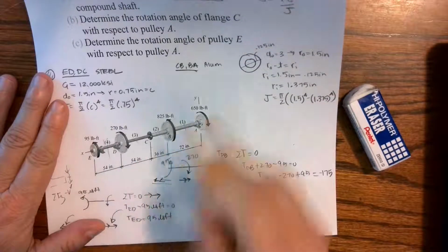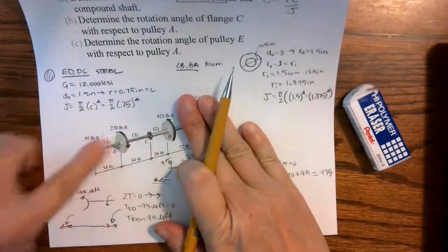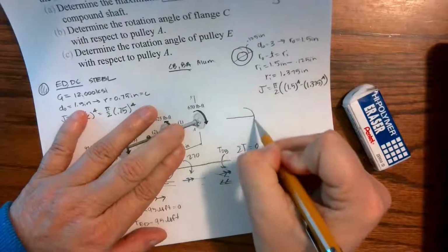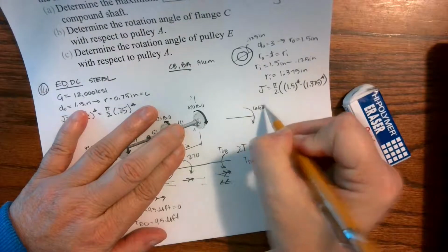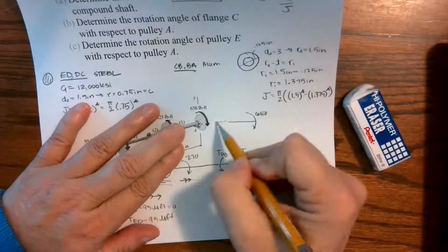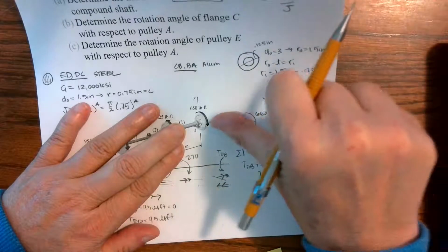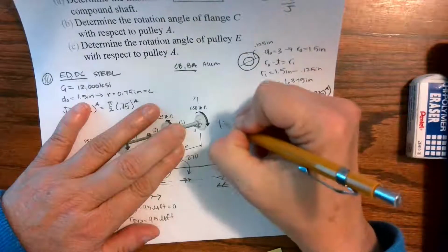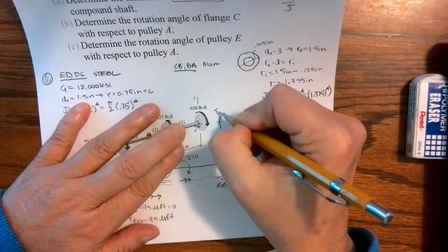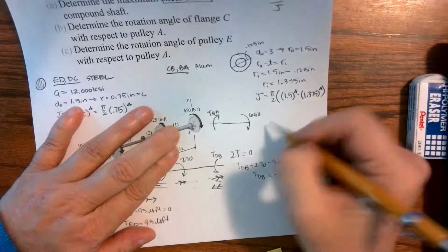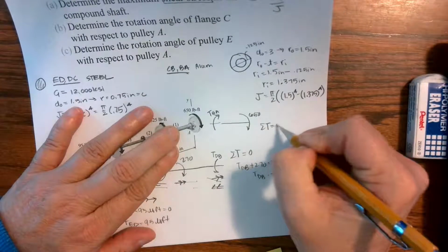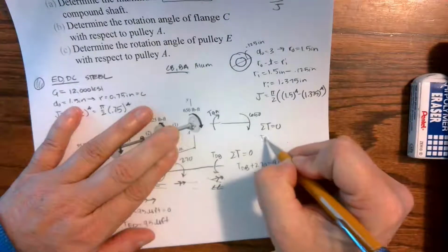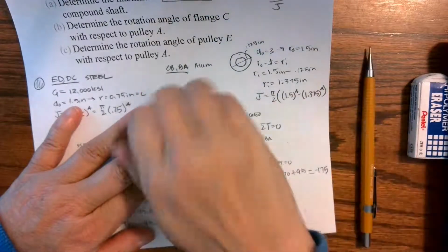Now I could go all the way across and draw this big thing, but because it's free to rotate on both sides, I can come back over here, and I have 650. Okay, if I'm looking at internal positive, thumb away from the cross section, circling to the back, that's my torque from B to A. And if I sum my torques, they have to equal 0. I'm going to start here, so I have a positive TBA. Okay, positive TBA.